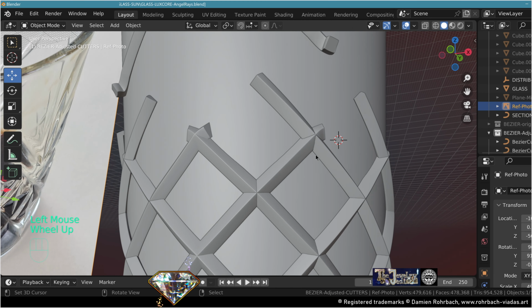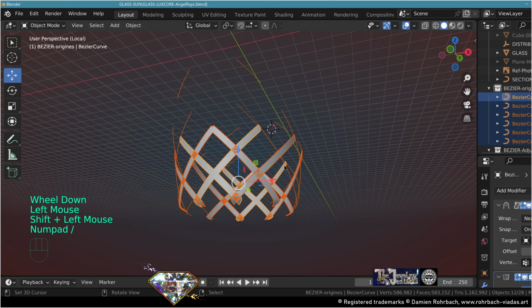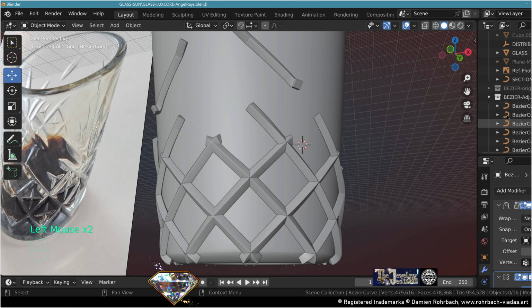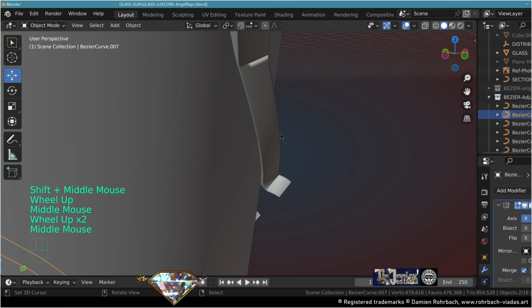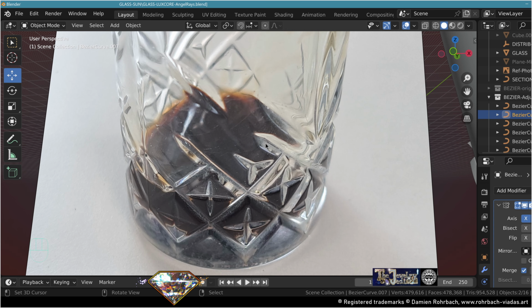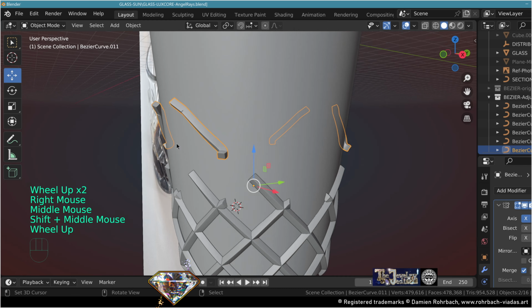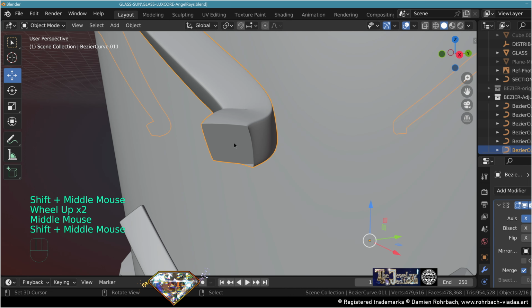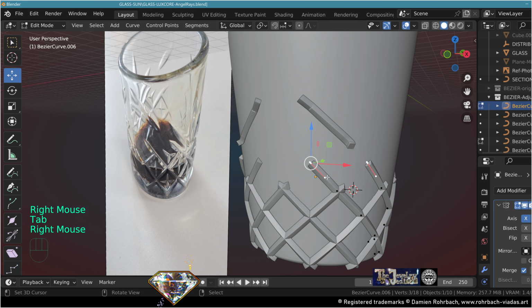All right, so here, organize yourself a bit. I made collections. These are the original Bezier curves. Then we made a copy of the beveled curves. And now a step I did already here. Don't forget that the endings are sharp, are pointy. So to do that, you can simply extrude the ending, and when making the boolean, we'll get that shape. So I did it there, but I still have to do it here.